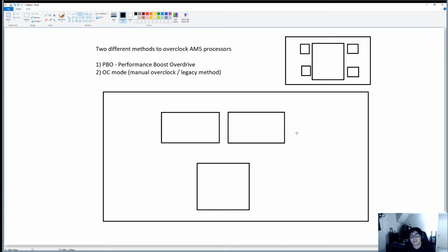They just put it there for stability, so that the additional support under the IHS makes the weight or pressure distribution on the actual processor dies more equal, as opposed to having only a single CCD and an empty space next to it. So I understand why they do that. They did the same thing with the EPYC processors and the first and second gen Threadripper. If you had anything less than the 32 or 24 core, you had dummy dies on there as well.